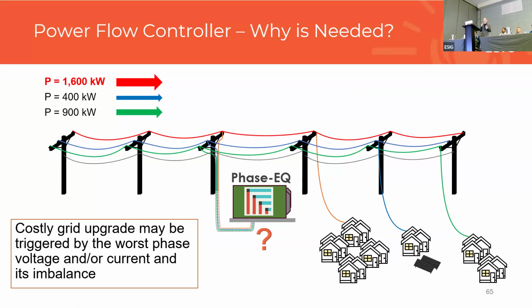In this case, we're going to look at systems that have imbalance, as many distribution systems do, and how we might be able to create a more balanced system in order to remove some of the constraints, such as worst phase thermal constraints. So if you have one heavily loaded phase, you're going to likely run into the thermal constraint first on that phase.